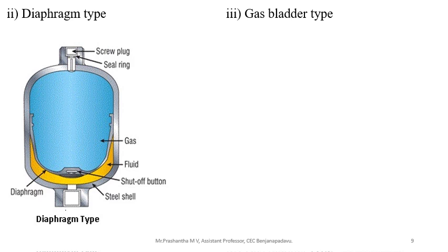When we go for a construction, it consists of a spherical body. Here the spherical body inside it, and a flexible diaphragm. The spherical vessel is separated into two compartments by a flexible diaphragm. This is the flexible diaphragm. See this one. One compartment is connected to the hydraulic system and the other is connected to the high pressure gas system. See here, this is for a gas, high pressure gas, and this is for the hydraulic system.